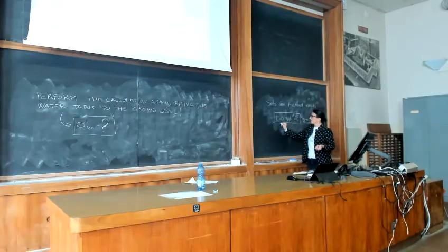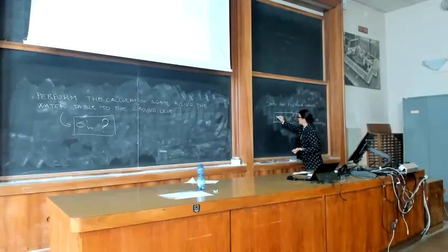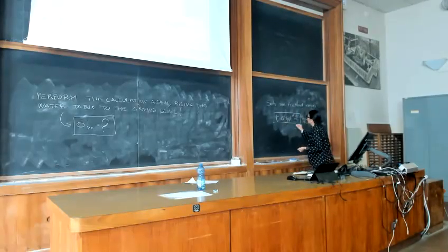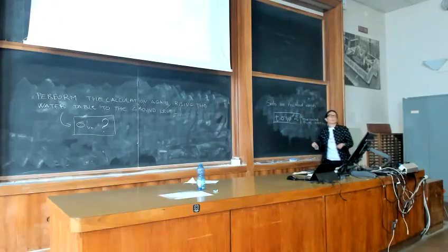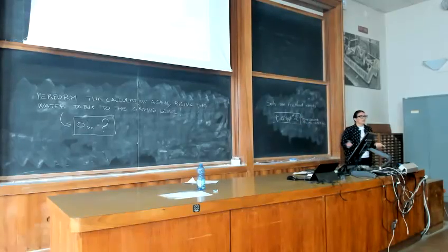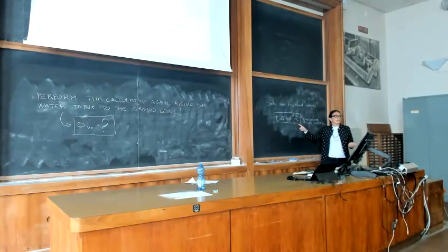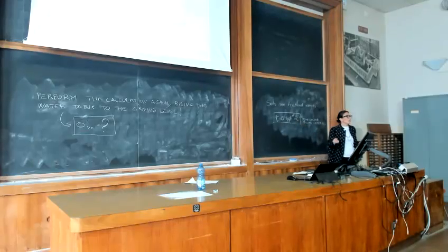Okay, where the stress state is provided by tau and sigma, while phi dash and c dash are soil properties, soil friction angle and the effective cohesion. Okay?